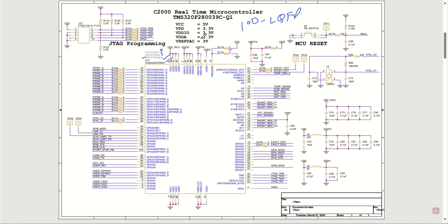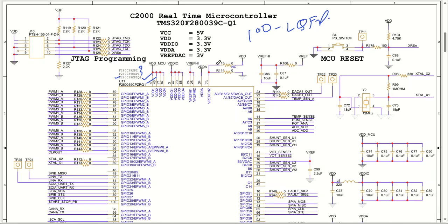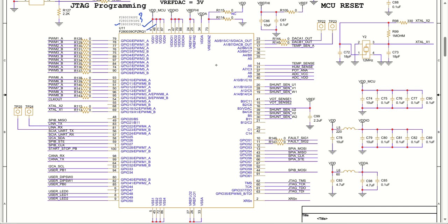As you can see, the very first thing that we have to do is design this particular microcontroller symbol. Okay, so as you can see, all the GPIOs are arranged on the left side, and a few of them are also put on the right side. Similar to that, we have power supply pins on the top side and power supply ground pins on the bottom side.